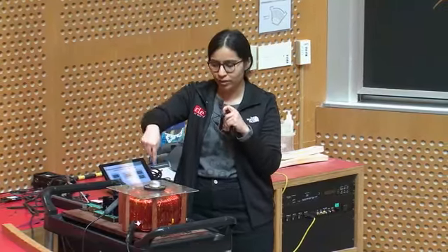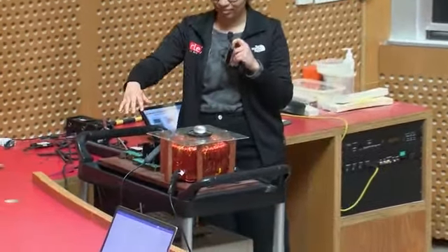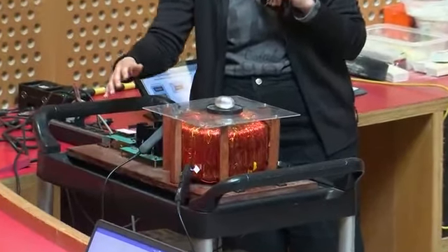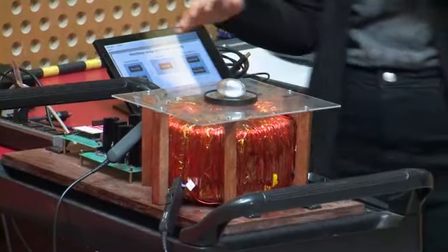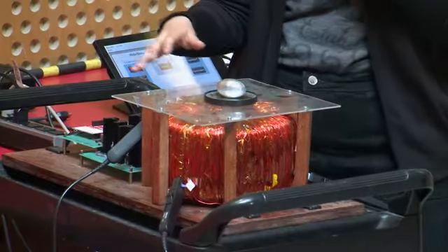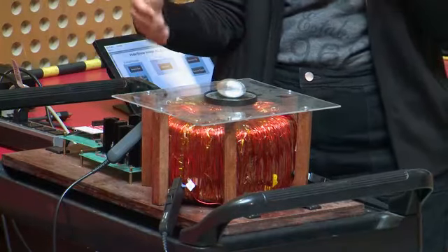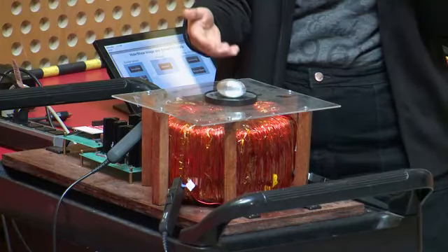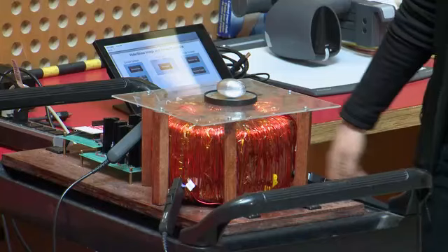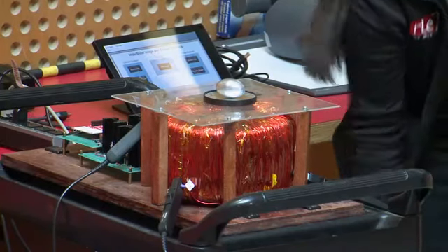For our rotor, we're gonna use this metal egg. And then on this side, we have our three-phase inverter with 6 switches, and this is our gating circuit. So what's gonna happen is that we're gonna create some rotating magnetic field using our stator, and then that's gonna induce some eddy currents in our rotor, that is our egg, and then it's gonna force the egg to spin. So let's start by trying to slowly increase the bus voltage and see what's gonna happen.